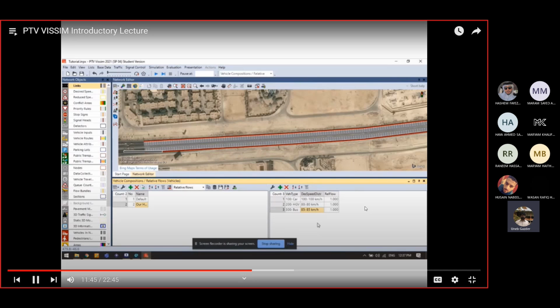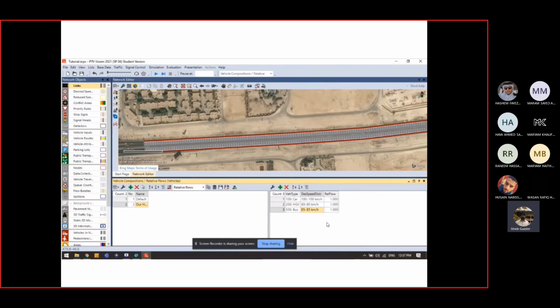Okay. This means the relative number of each sort of vehicle that is going to be input onto your road. So we'll start with cars. For example, from the road, you'll have taken the data of the number of heavy goods vehicles compared to the number of cars. So you'll have a certain percentage of heavy goods vehicles, a certain percentage of buses, or they can be combined. That's also fine because I think that's the data you'll be taking from the road. And you'll have a percentage of cars. So let's say that the percentage of heavy vehicles in total is 0.2. So you can divide that equally among heavy goods vehicles as 0.1 and 0.1. And the rest, the 0.8, which is 80% of the vehicles, are going to be cars.